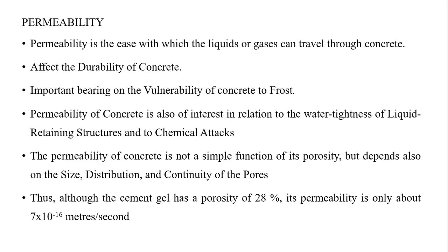So, as I said before, it should have some pores. Pores are called holes, so that the liquid can enter into the stone. Similarly, the permeability of the concrete depends upon the size and distribution of the pores. So the range is about 7 into 10 to the power minus 16 meter per second, and the porosity should be about 28%.